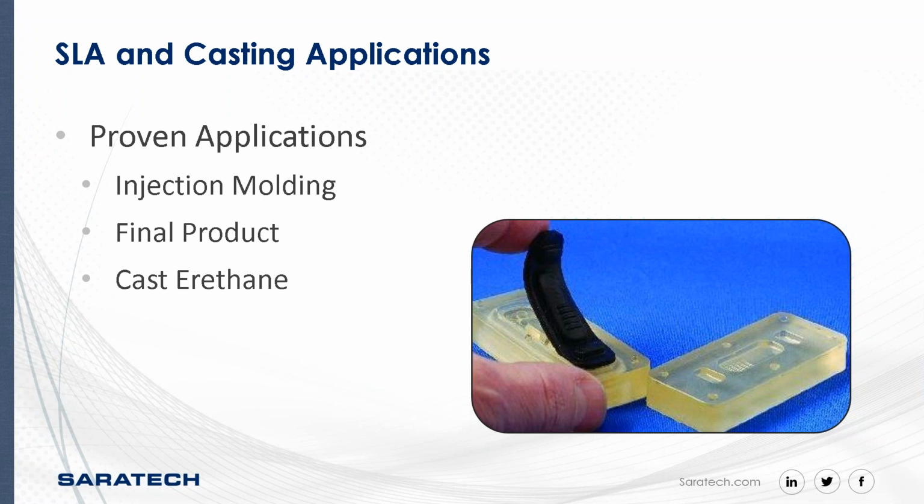Another advantage is that if there are changes that need to be made, you can just update the design and print a new SLA mold, and the new parts are ready for testing in a couple days. You can do cast urethane, silicone, the material properties are many. And what does this solve? This solves the fact that you can, at the end of the day, have a process that's already been certified. These aren't new things. These are just used in different ways to advance your manufacturing process.